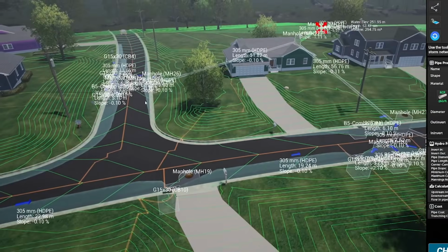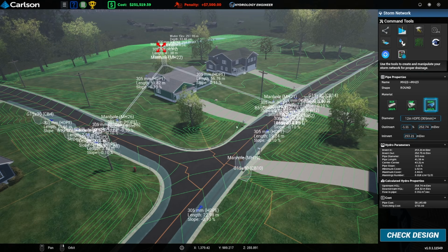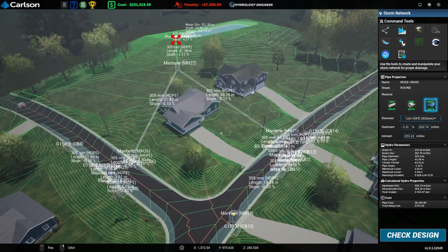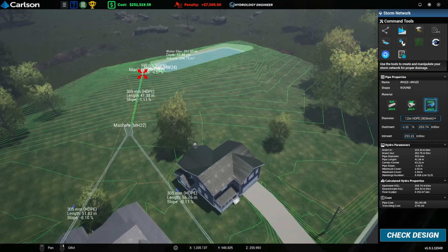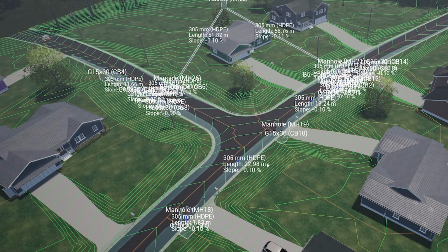Generally a little pipe flooding isn't as bad, so you should think of it as we design our network for a 1 in 30 year storm, and then we just make the pond a bit safer, rather than designing everything for a 1 in 100 year storm but then making our pipes not as safe.